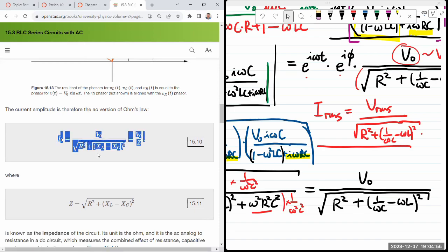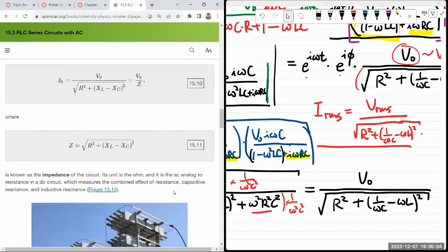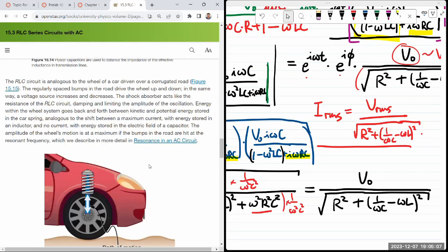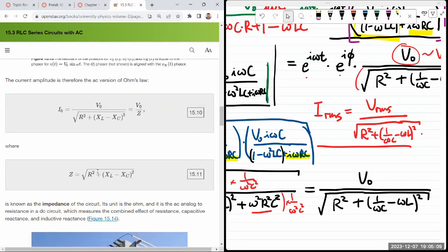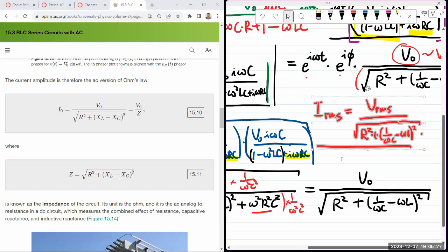And this is how your textbook wrote it. And you can see hints of that here, especially in this rewritten form. And this is G here, it's that. And did they ever plug in the actual quantities? Okay, they didn't, but they did cover XL. The impedance of an inductor was omega L, and the impedance of a capacitor is 1 over omega C, and that's this. The minus being swapped around doesn't matter because we are squaring it anyway. So yes, this is the same formula that's in the textbook.